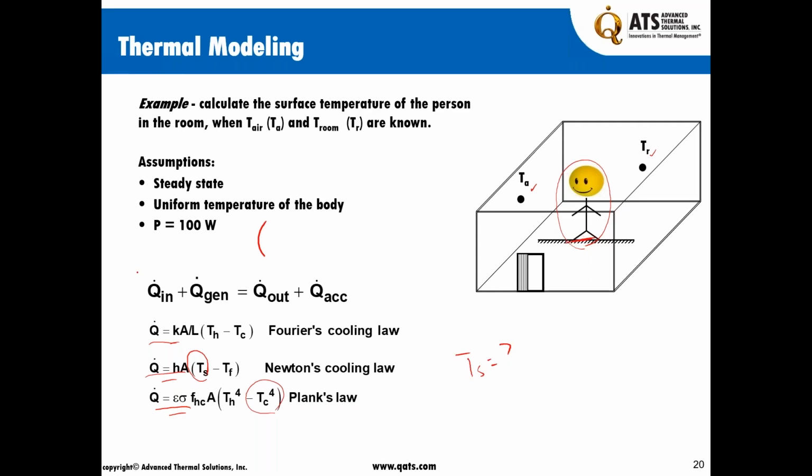And you'd find when you go through this calculation, and this is the integral model of the conservation of energy, all the heat that's coming in, which in this case is 0, there's no heat coming in, that's generated is about 100 watts. And what's going out is by convection and conduction. And we make an assumption the problem is steady state, so there's no accumulation. This is the dt divided by the time. So we assume that this is steady state.